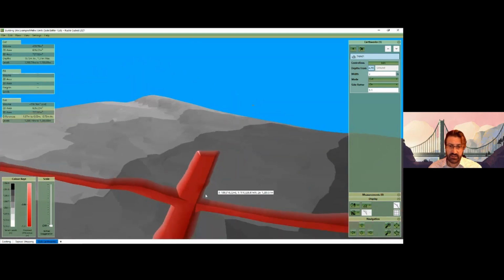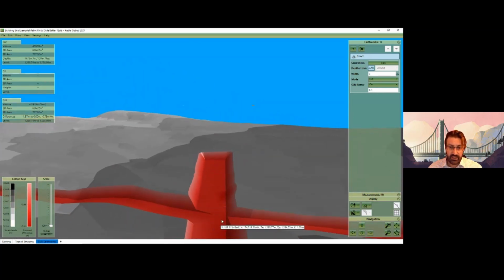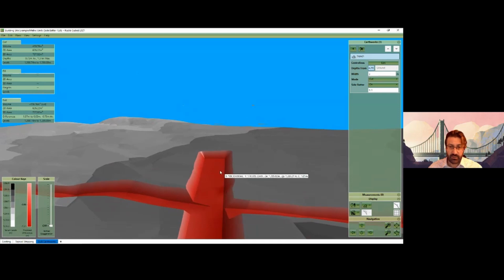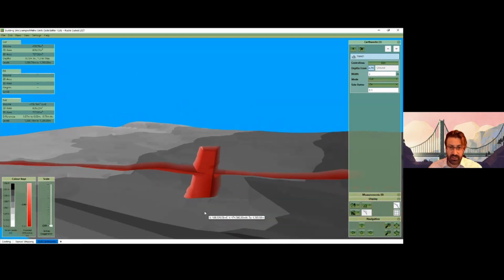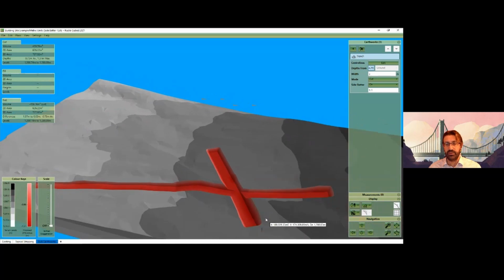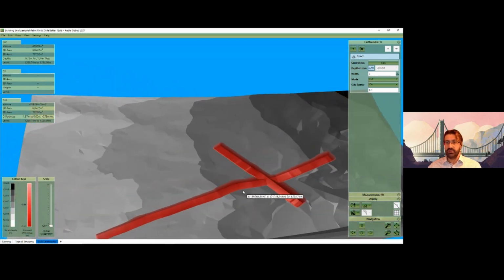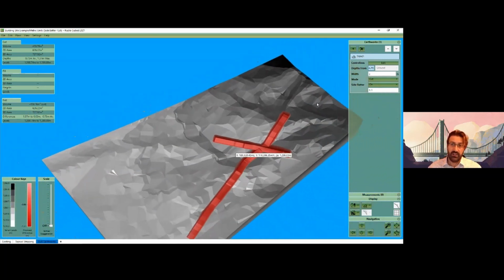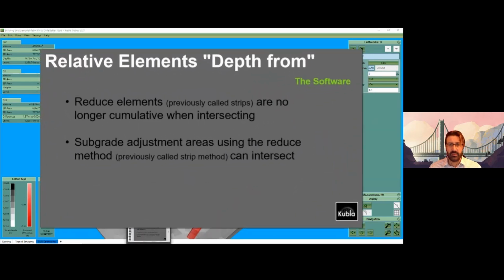So in this case, you can see that where they're crossing over, the one at 1 dug out deeper, but it's not gone twice. It's not doubled the operation. So using these tools, you can do pretty much any trench network you like. You still have the ability to add multiple trenches or multiple berms and paths, but you can define a whole trench network at 1. The reason that you might want to split them up is that they're different widths, because a trench network shares the same width. So that's something to think about.